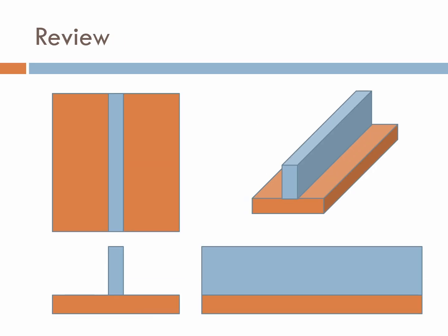Okay. Now, same thing here. This is just a review real quick. So, how do you do this? Just be sure you know what we got going here. This is your pictorial view, and you're looking at it and you say, okay, how do I want to show this? If I handed you a T-joint and you started looking at it, what gives me the best view, gives me the most information about what I'm doing? This view right here, so that becomes my front side. That's my top, that's my side.